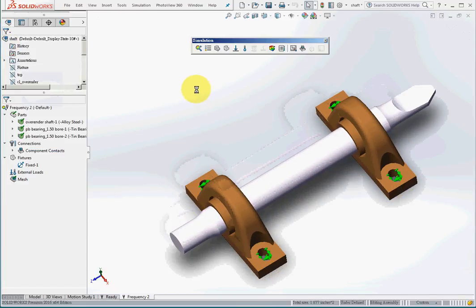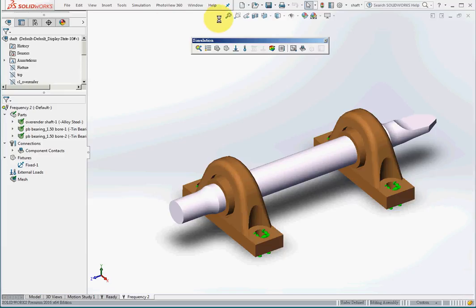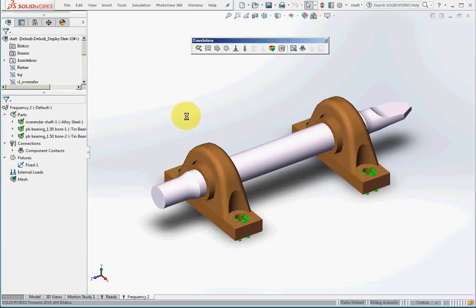surfaces. And now I don't need to apply any load, because natural frequency means that the external force is not taken into consideration. By natural frequency, it means that the structure vibrates on its own without any external load. So I don't have to apply any load.